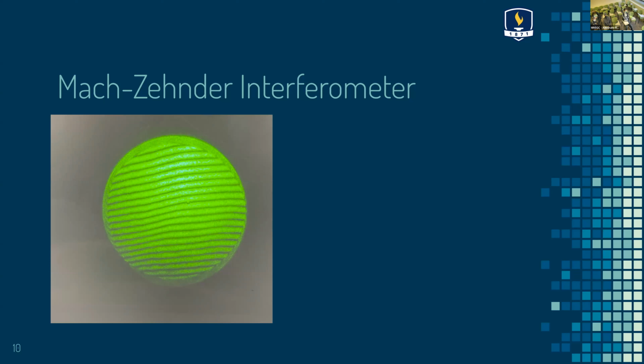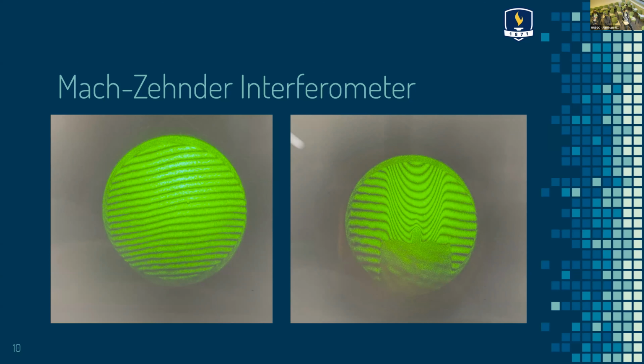Now, as we have the variable density, it actually allows us to move these fringes. So here we have a candle placed in the apparatus. As you can see, the lines are all distorted, and by counting how far those lines have moved, we can infer backwards to make determinations about the density field, and therefore the temperature of what's going on in the actual flow region that we're interested in studying. So it's a little bit more quantitative than Schlieren imaging, but it's harder to view a big area. It's the trade-off.